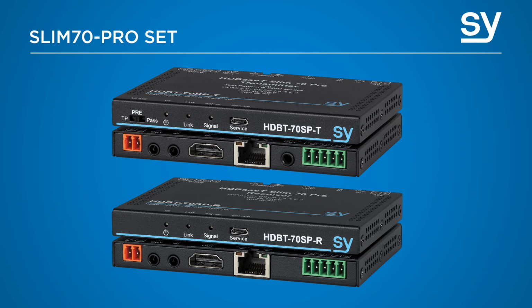By default, out of the box, the SLIM70 PRO will be set in auto scaling mode, so no need to change anything if you don't want to, as the SLIM70 PRO will sort out what is the best applicable format to transmit by checking the source and the display capabilities as well as the CAT cable length of the installation itself. It will set itself to the optimum scaling format. You choose how you want to use it, either manually or automatically.